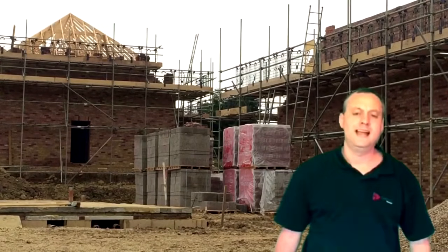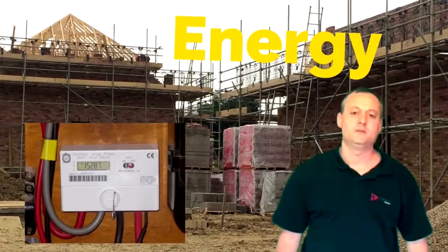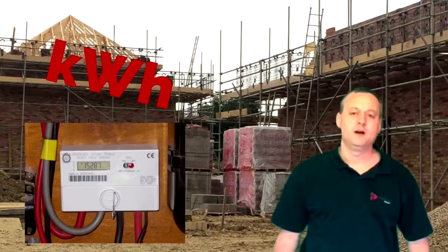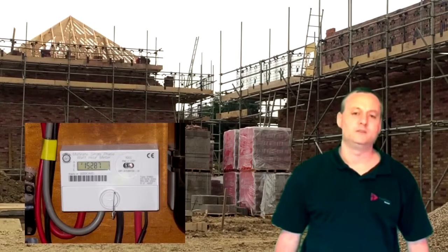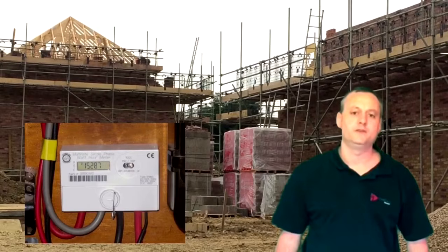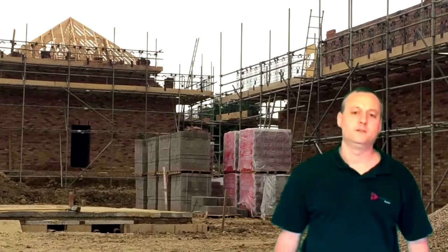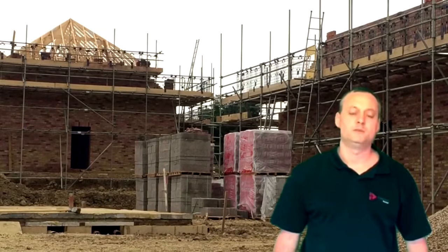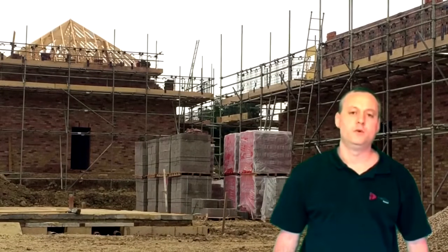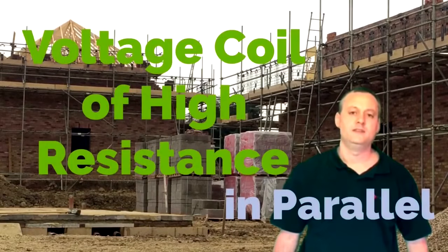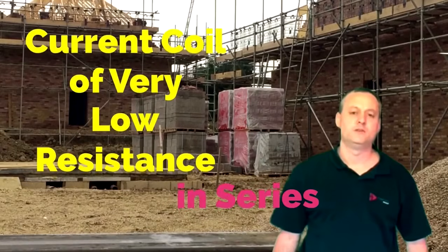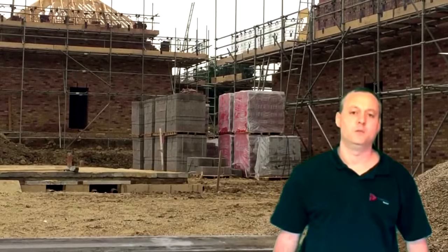We briefly looked at energy in the form of an energy meter, in other words, the electricity meter at home, and we said that energy is the kilowatt hours, and we went on to work out basic calculations to work out the kilowatt hours used by a consumer. We saw that a watt meter, in other words, to measure power, had two coils in it. One was measuring voltage and one was measuring current. And the voltage coil was a very high resistance and the current coil was a very low resistance. Again, these basic questions on a watt meter come up in the section on power and do not require a calculator and are worth remembering.